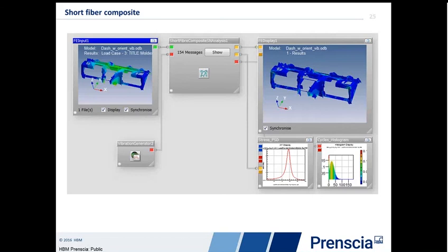In this case, the PSD was an excitation in terms of gravity loading on the dashboard. So we had mount points on the dashboard, the polymer dashboard, where it was matched to the car body, and we have basically gravity oscillating based on the PSD. And coming out of this, what we have is maps of life and damage. We also can go off and extract out of critical locations things such as the PSD of stress, the distribution of cycles, and we'll see these as we go on later on as well.